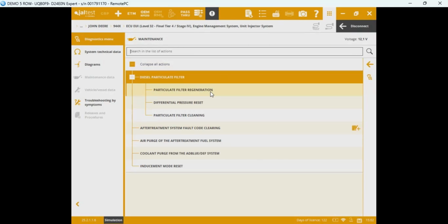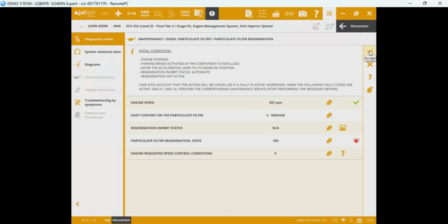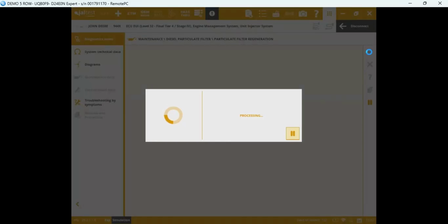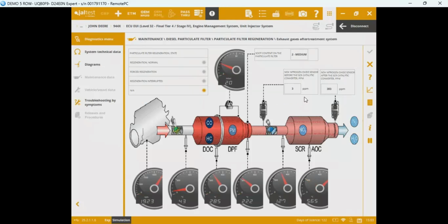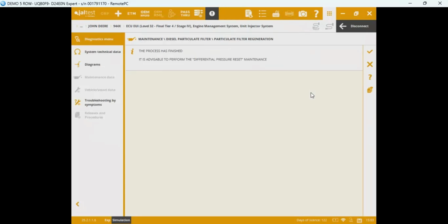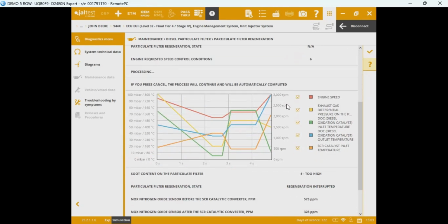After we have done this, it's always advisable to run a particulate filter regeneration. If we have already replaced any system components that were faulty, we can quickly jump into our forced regen, right? Again, we need to check and meet some criteria there. Let's just say we are on point. We can start forcing this regen. Regens can take around 45 minutes to 1 hour, depending on the system, and then we're active, running. We're going to be sensing live measurements such as particulate parts per million, NOx sensors, pressure sensors, and differential temperatures on the catalytic converter and SCR, and we're going to have a clear picture of what happened during that particular regen, right?